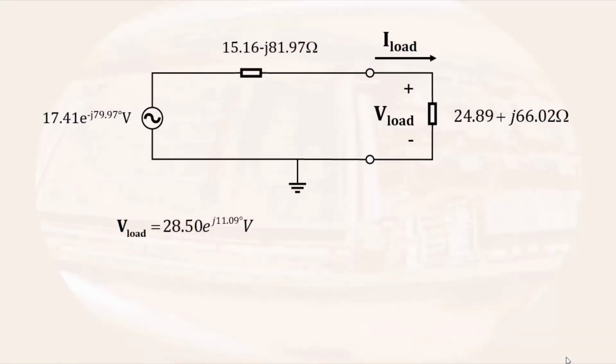An interesting thing has occurred here in that the magnitude of the load voltage is higher than the equivalent source voltage. If this troubles you, you should determine the voltage across the source impedance and then do a KVL loop to verify the voltages add to 0. If this does not trouble you, you probably need to perform the KVL calculation. Either you are not troubled because you understand resonance, which we have not talked about, or you have missed something fundamental along the way. When energy storage devices are involved in a circuit, it is possible that the energy exchange between the devices, like capacitors and inductors, can result in the magnitude of individual voltages being higher than the source. Kirchhoff's voltage law will always be true, however, so all of the voltages in any loop will still add to 0. Back to the power calculation.